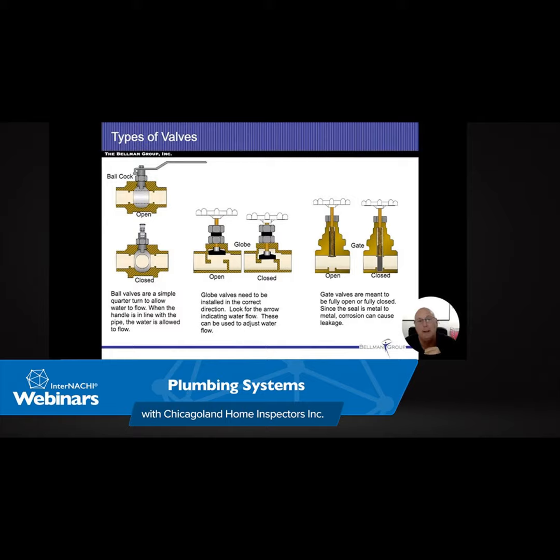Great add. Thanks, Mark. With these electric water heaters, we don't necessarily need a dip tube. We don't bring the water in from the top. If you notice, the cold water line is actually just plumbed straight through the outside and comes in through the bottom anyway. So we're not worried about finding that dip tube. And as we go up and out, the hot water comes out of the top. So we're doing the same thing that we were doing before: bring the cold in at the bottom, hot at the top.